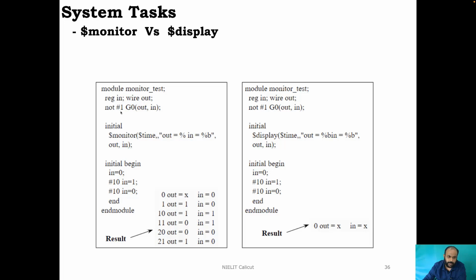So whatever you give to the input of this NOT gate, it takes another 1 nanosecond of propagation delay to reach the output. So at 0 simulation time unit there is no change in the output, and the output will be driven with the default value. When the input changes to 0, after 1 nanosecond, the output will become the opposite value of it.